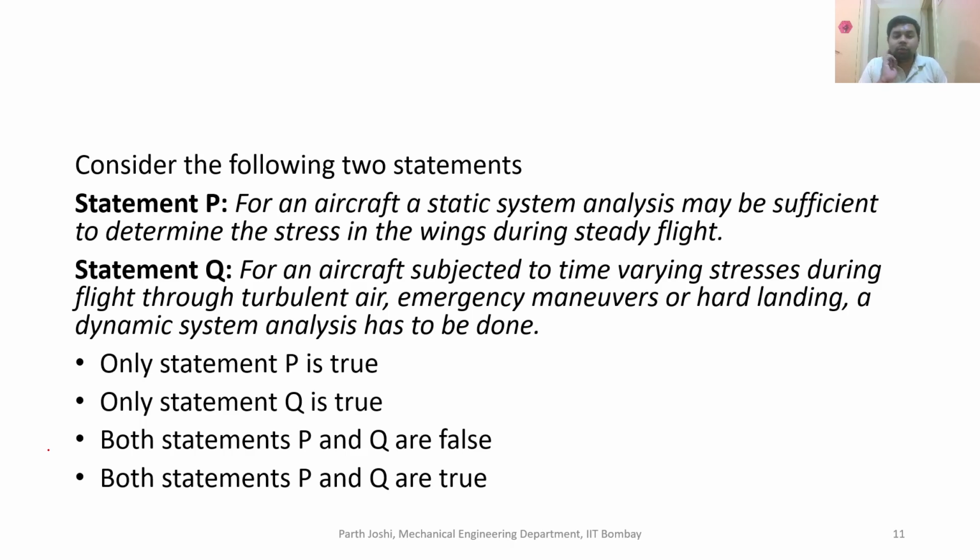So as we just discussed, in steady flight the forces won't change with time, so we can use just a static analysis to calculate the stresses in the wings. But in the other phases of flight, when the aircraft is taking off, climbing, doing the descent or landing, or flying through turbulent air, or in emergency maneuvers or hard landing, etc., we will have things which are changing with time. So in those cases, we need to do a dynamic system analysis.